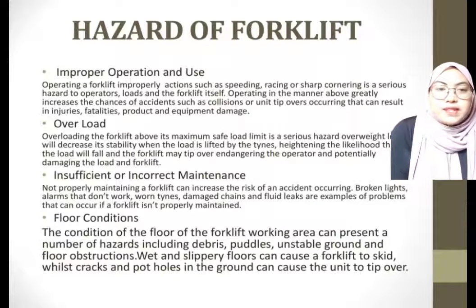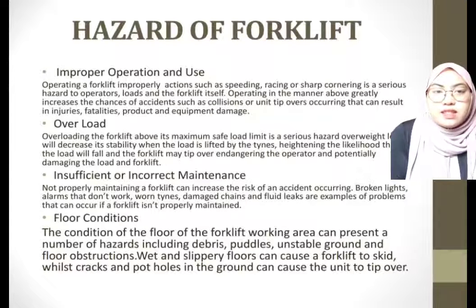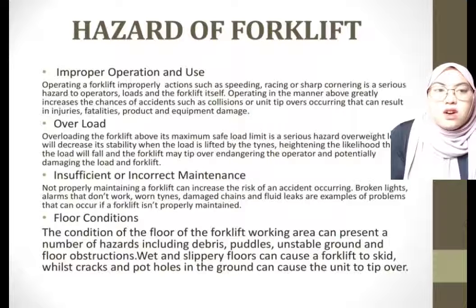Today I would like to present about hazards of forklift. Firstly, improper operation and use. Operating a forklift improperly, with actions such as speeding, racing, or sharp cornering, is a serious hazard to operators, loads, and the forklift itself. Operating in the manner above greatly increases the chance of accidents such as collisions or unit tip-overs occurring, which can result in injuries, fatalities, and product and equipment damage.